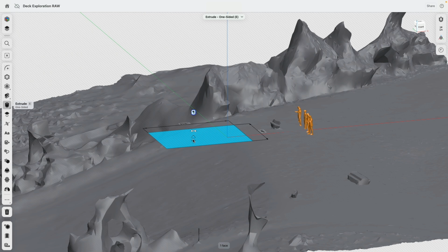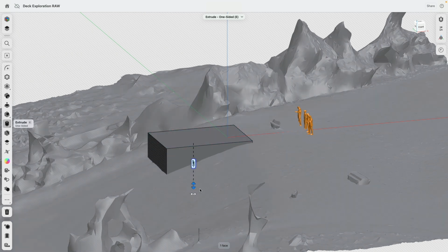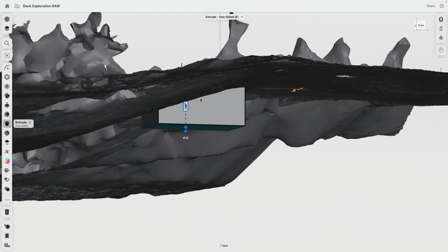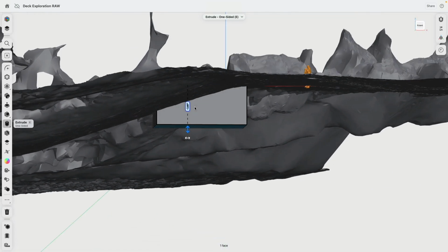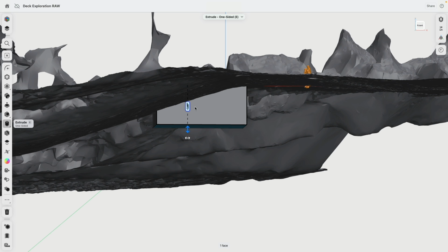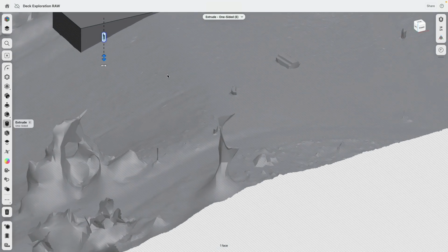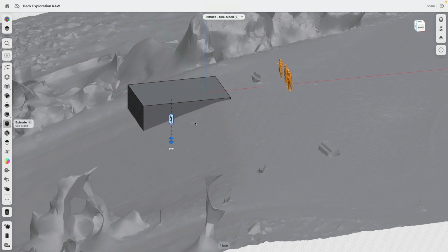Then we select the sketch profile and we are going to extrude this one down. How much? 160 maybe in this model. That is fine. Now, based on where you're living, are you in a hot climate? Are you in a cold climate? The depth is going to change because you need to calculate in how far during the freezing time, so winter, negative temperatures penetrate the soil. And this is something that is really important when you do an actual project and it's being constructed. Right now, this is really in the conceptual phase, so something like this is totally fine. Perfect.